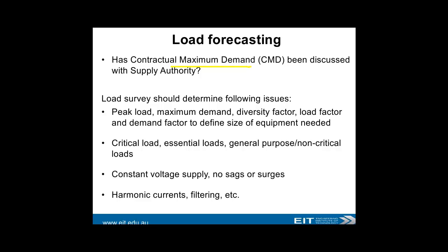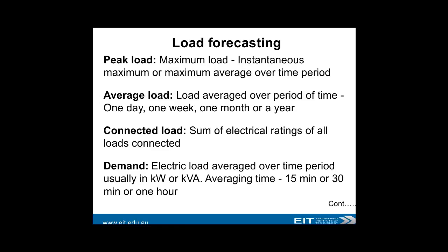Make sure you've spoken about contractual maximum demand. That's always a very big chestnut for the supply authority. Do a load survey about peak load, maximum demand, diversity factor, load factor. I'll briefly define these in a tick in the next part. Critical load, essential load, general purpose. Constant voltage supply, no sags or surges, and obviously harmonic currents and filtering.